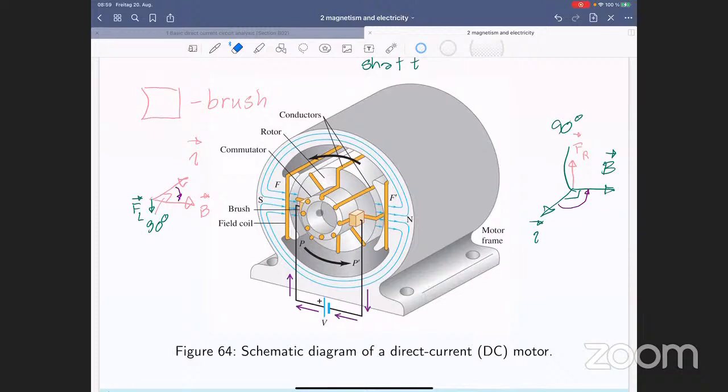Yeah, that's the end of the day for the direct current motor when it just disrupts all the time, and this part just disappears from the system. The one thing that we could do to this broken motor is that we just take it out, and then we replace the brush.